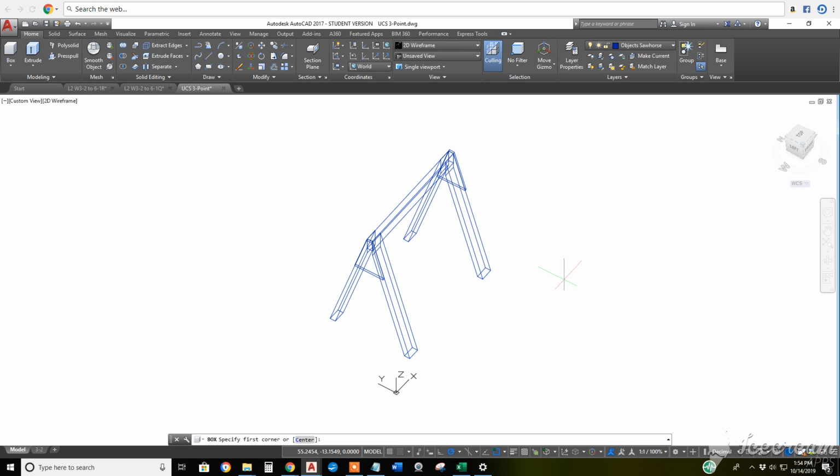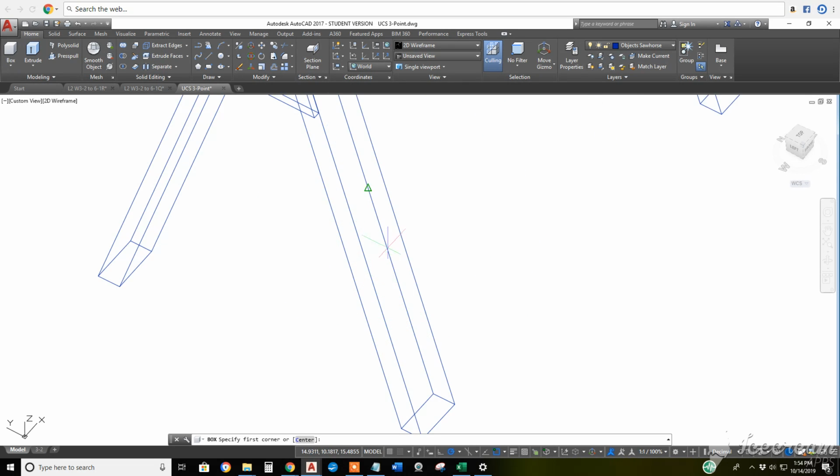In this video, I want to show you how you can create a new XYZ orientation. You can have the XY plane on any surface you want. It doesn't have to be on the floor, so to speak, of your drawing. I want to put, say, the XY plane on the surface of the side of this leg so that I can drill a hole perpendicular to the surface of this leg, maybe to hang an extension cord on the sawhorse.